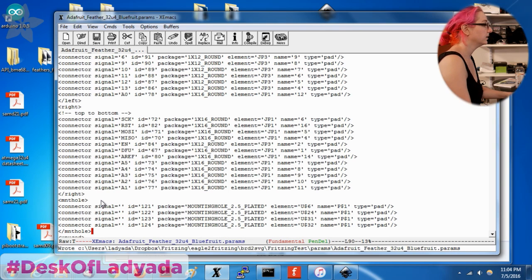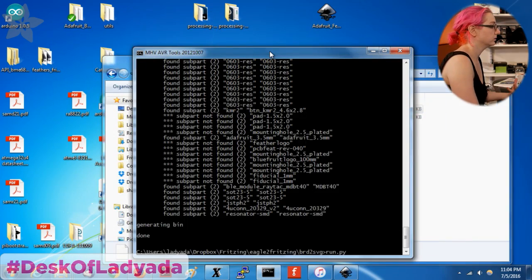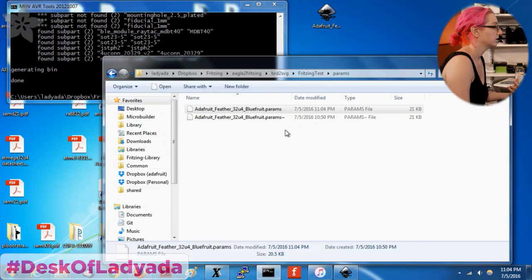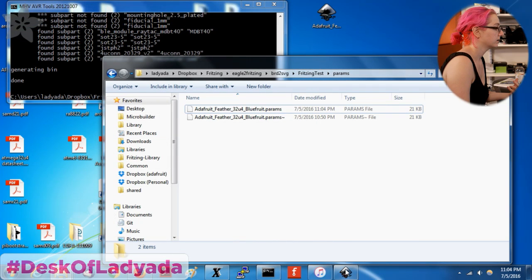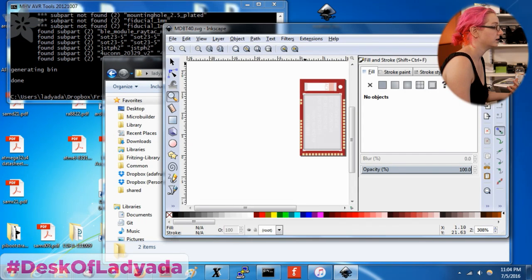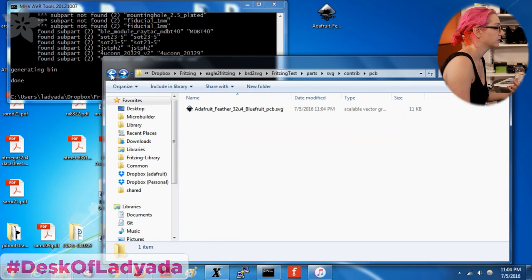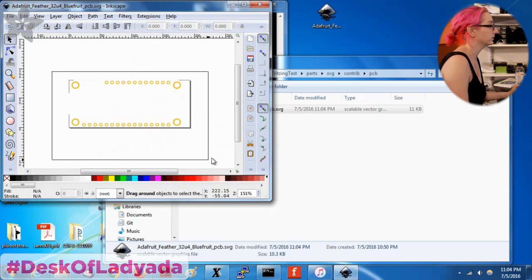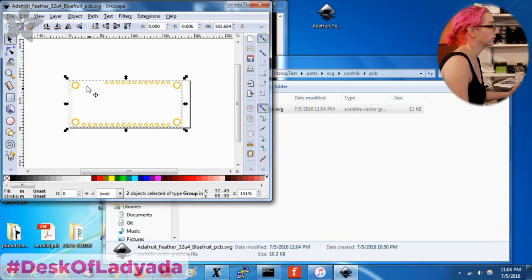It can be called anything, but this basically says it's not unused, I want them to be rendered and I want them to exist. So then when we rerun the tool, you get to run the tool a lot. Okay, we're done editing this. And then we reopen the PCB file. This time, it gets all the mounting holes. So see, like these 4 mounting holes were not there before, but they are now.